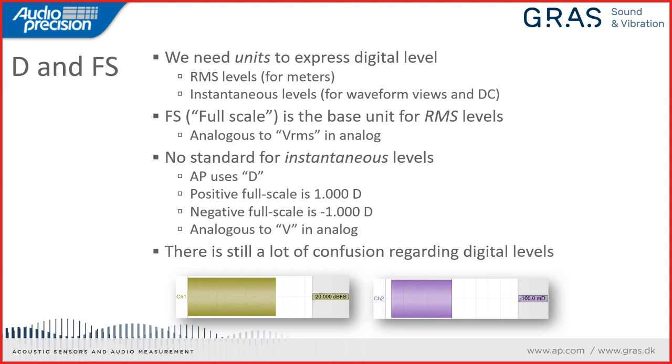Yeah, that's a great question. So what's actually going on behind the scenes inside of an APX analyzer is up to 192 kilohertz sample rate, or roughly 90 kilohertz bandwidth, we're using one set of analog to digital converters. And then to go to the next step in bandwidth, we actually go to a completely different converter that operates at a much higher sample rate. So that's why there's that sort of step function: internally to the APX555 there's a gear change.